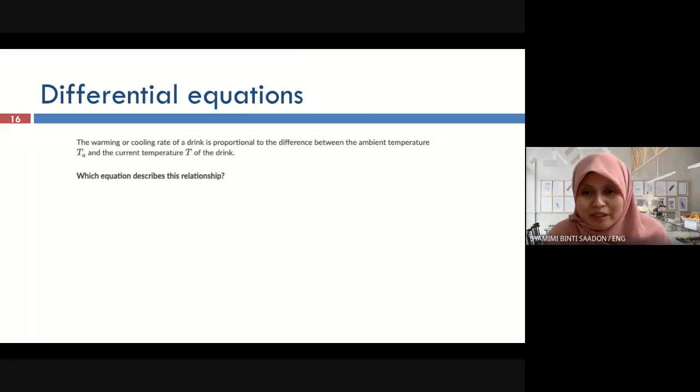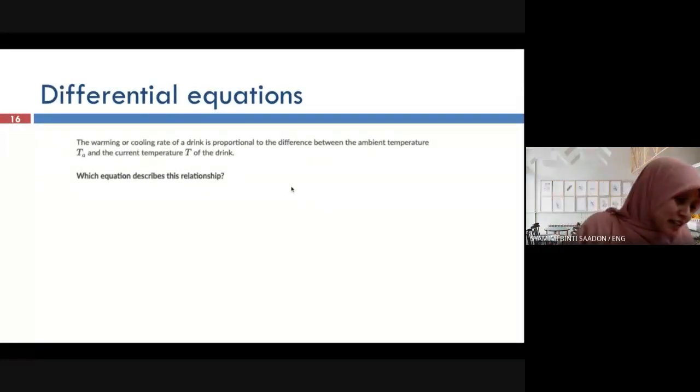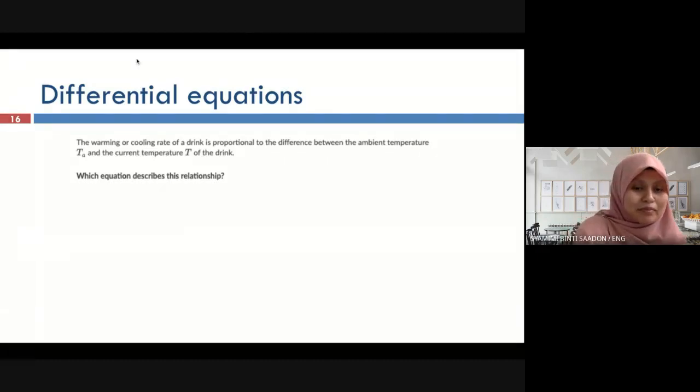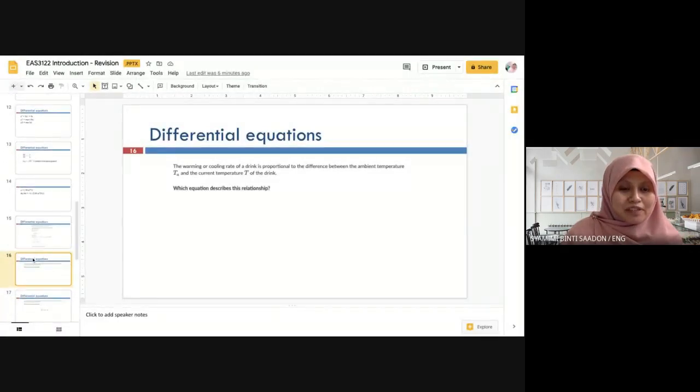dQ, heat, H or Q. Normally the physical symbol for heat is Q, because H is actually the heat transfer coefficient. But it's okay, it's correct. Since we have T, temperature, here, it's easier if you write dT over dt, because we want to write it in terms of a differential equation.